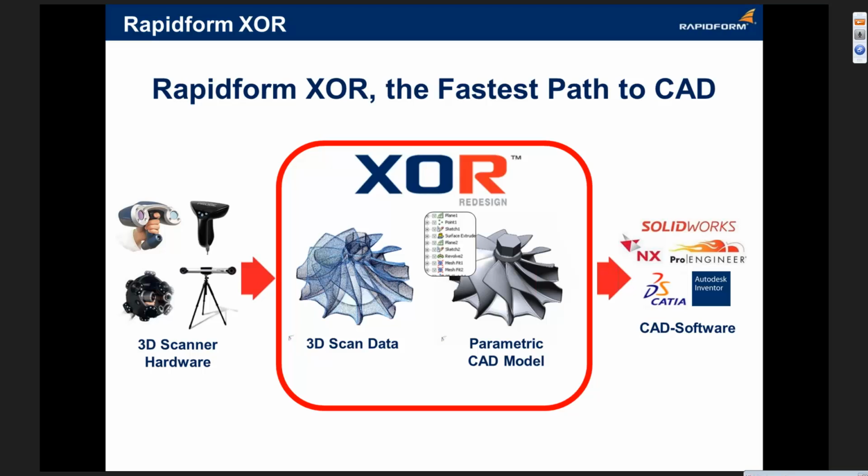And then we can output the native CAD file using a live transfer process, or we can store several neutral file formats which you can load in any known CAD software. The main CAD software we support is SolidWorks, Unigraphics NX, now Siemens NX, ProEngineer, CATIA, and Autodesk Inventor. And we support also STEP, IGES, and Parasolid file formats. And for input we support many scanner formats, among those the Creaform scanner hardware directly.